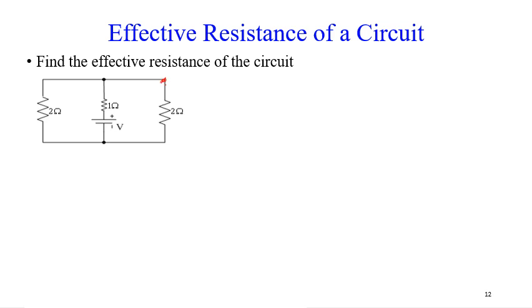Let's consider this resistor. If I circle this resistor, we are identifying parallel resistors. If I circle this and this, they are in parallel because 2 and 2 are in parallel. So what do we do? We say R parallel is equal to 2 times 2 all over 2 plus 2. After doing this, what do we get? 2 times 2 all over 2 plus 2 is equal to 1, which is 1 ohm. So we have to redraw the circuit again.